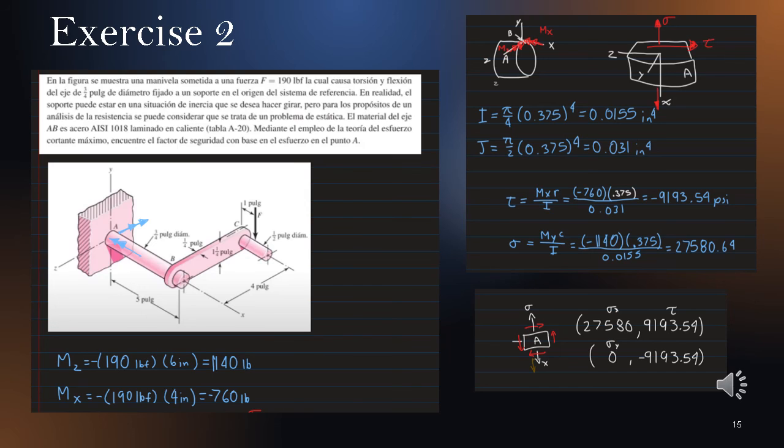We now understand that the normal stress of the y-axis generates tension, as we see on the diagram, and that the shear stress in the axis is positive, as it is clockwise. Now, as we already understand the formulas, all we need to do is enter these values on the Excel sheet, and we can obtain the main stresses, maximum moments, and maximum shear stress.